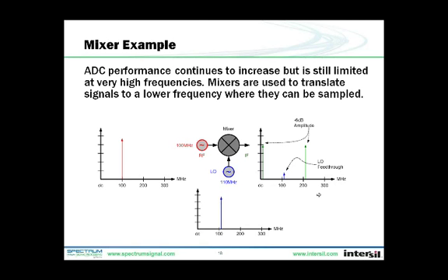So one very important element in today's receiver is a mixer. The mixer provides the frequency translation function in the receiver by multiplying its two inputs. When the RF input is mixed with the local oscillator, or LO, the output will include two signals, RF plus LO and RF minus LO. In an ideal mixer, that's all you'd see, but in the real world, you also see a little LO feed-through, which is just an attenuated version of the LO.